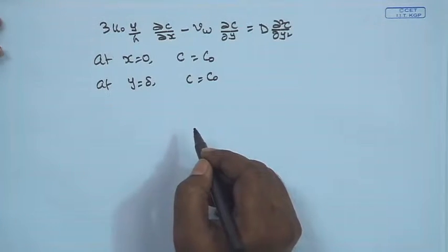But as we have argued in the last class, we are dealing with a system where the solute has very low diffusivity and hence very high Schmidt number, and the mass transfer boundary layer thickness is inversely proportional to the Schmidt number. So, we are talking about a mass transfer boundary layer thickness which will be around 1% of the total channel dimension.